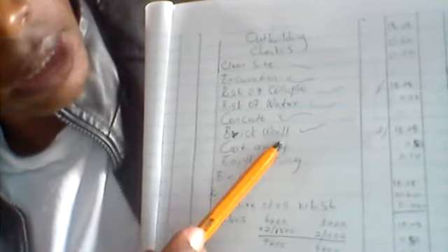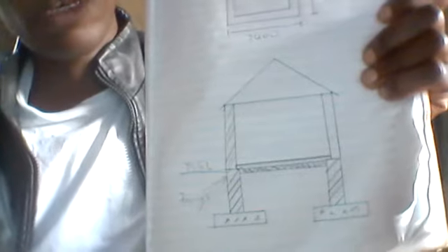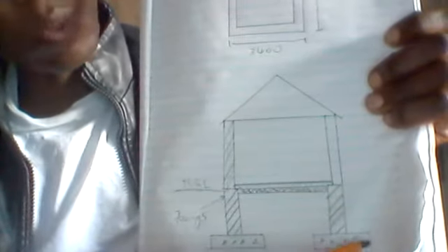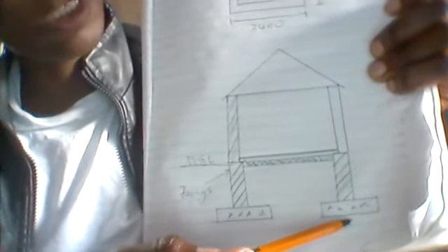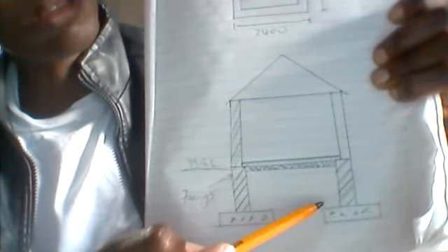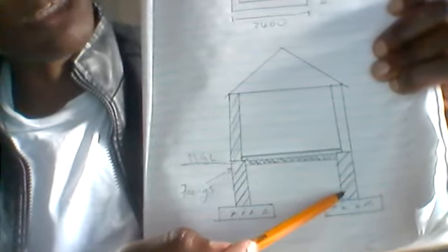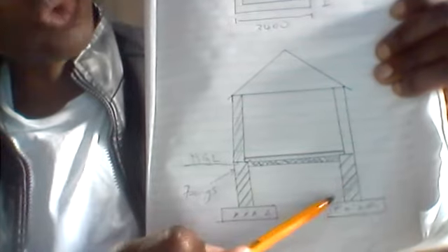So now let's move to backfill. If you can check on our checklist, I forgot to write the backfill before the cutaway. So on your checklist, just add the backfilling under the brick wall. So let me explain the backfill, guys. When you backfill, this is the width of your trench, which is 600. So we are going to backfill these two sides of the trench. You take the width of the trench, which is 600, you minus the thickness of the wall, and then you divide it by these two sides.